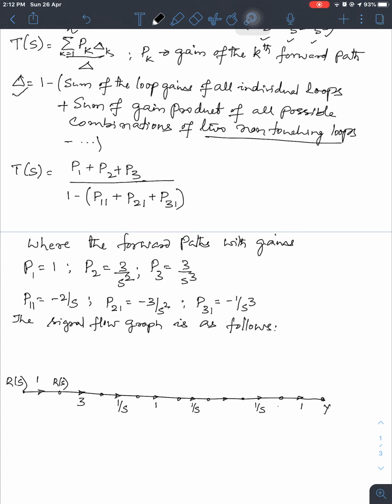So we'll denote this node as x1. This is x1. Alright. So this node which precedes x1 obviously would be x1 dot. So x1 dot, when pass through an integrator, you will get x1. So I will take a unity here.